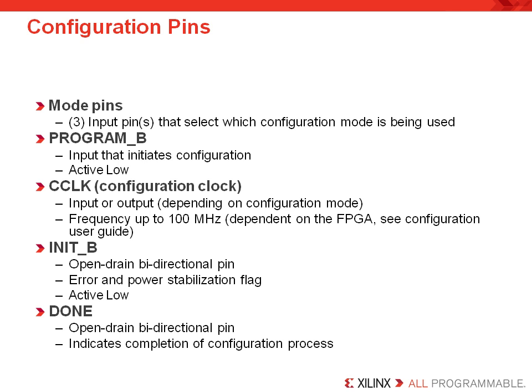The done pin indicates the completion of the configuration process. It's bidirectional, so the user can delay the startup sequence. After configuring the FPGA, the starting of the FPGA is often controlled by the user to control the releasing of the entire FPGA system to operate. On a side note, in case you don't know, BitGen is the bitstream generation utility included with the ISE software. It is used to create a bitstream from the implemented design and is used for configuring your device.